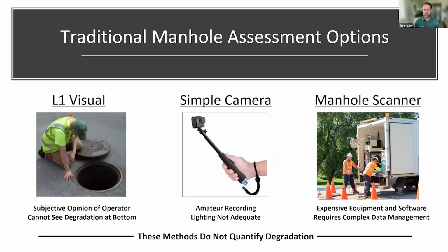Here's what you're doing, best available tech. You've got, hopefully, a field of operators who are going out and taking a look. We've got the flashlight up top, making sure that structure, that picture that we just saw of the crack, we want to keep an eye on those. And hopefully that's not a surprise when we send you a picture of that and identify it. Maybe we're getting a little tricky and starting to use a camera on a stick. So at least I get a little bit better view of what it's like 20, 30, 40, 50 feet down in these manholes where it's really tough to assess it from the top.